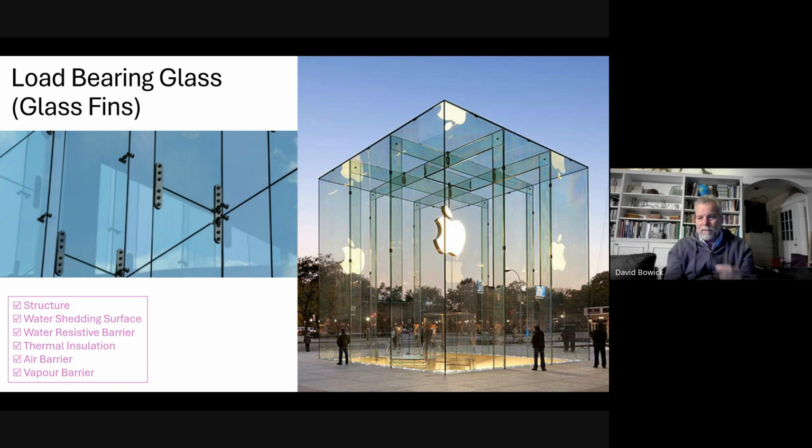You see the other rules we were talking about: L over 180, L over 240, L over 360 are normal deflection limits. For glass, it's more liberal than that because there's no finish attached to glass. It is the finish, and glass can tolerate a lot of movement. So load-bearing glass, we might have 4 laminations of 10-millimeter glass, but then it can be made into an insulated glazing unit as well. So you might have 4 10s, an airspace, and 2 6s, or something like that.